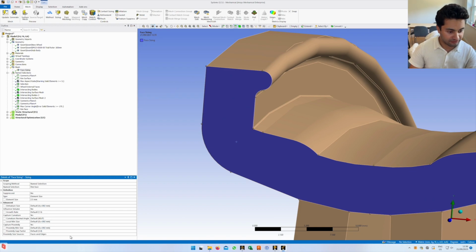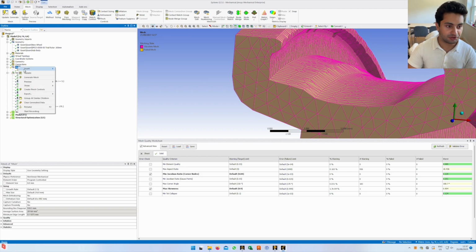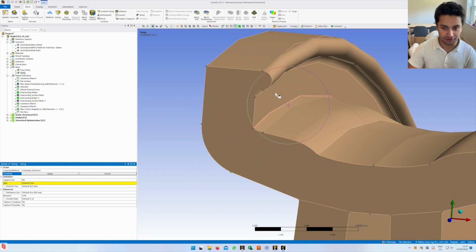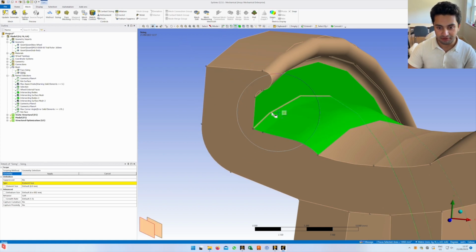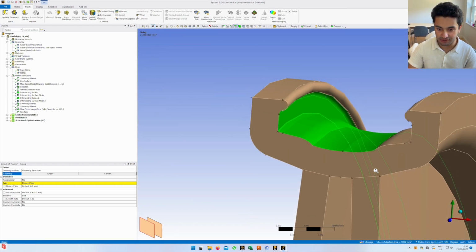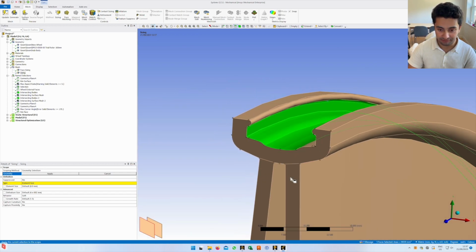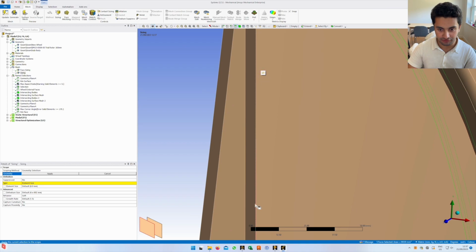So yes, we've pretty much gone over the relevant options on the sizing sub option in the mesh. In the global section, we've got a few more options, and again, I would go in and create another sizing one, and maybe all of the rim surfaces we want to be a certain size, because that's where all the loads are. We'll need more detail there probably, because there's greater deformation.